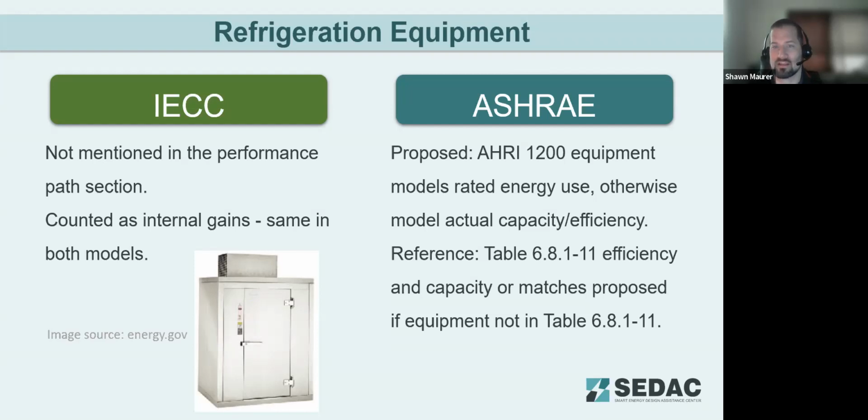And so it does have the ability again here, where IECC, these internal gains are the same between models. Ashrae adds a little bit more complexity to the model for modeling this refrigeration equipment, but gives you a little bit more energy savings potential between your standard design and your reference design for that trade-off.